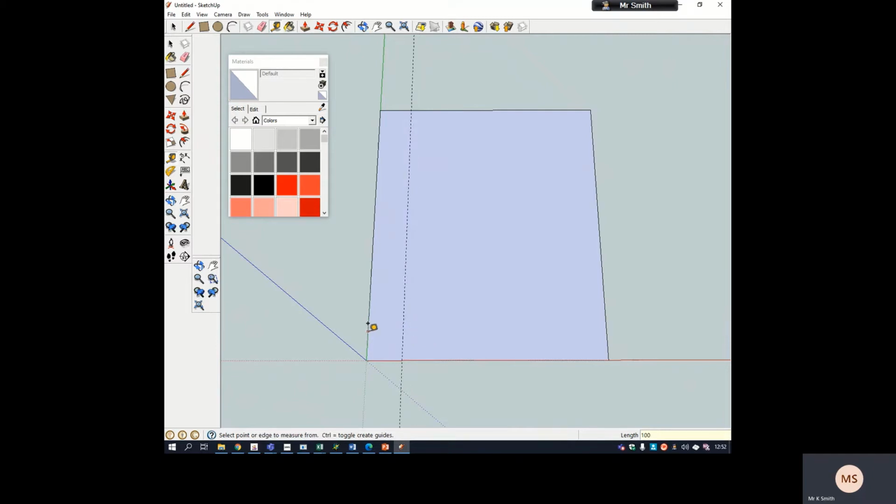So what I did here is I clicked on the line, the outside line, and then dragged across and then typed in 100 into length, and I'll do the same on this side. So drag in, type in 100, and then click enter, and it'll find that spot for me. And the curve, it's almost like a circle, but it's only like half a circle. So again, if I drag up now, instead of typing in 100, I'm going to type in 50. I know that my curve is going to go between there and there.